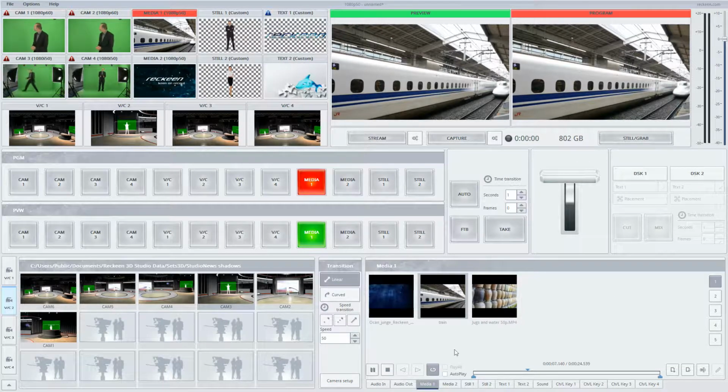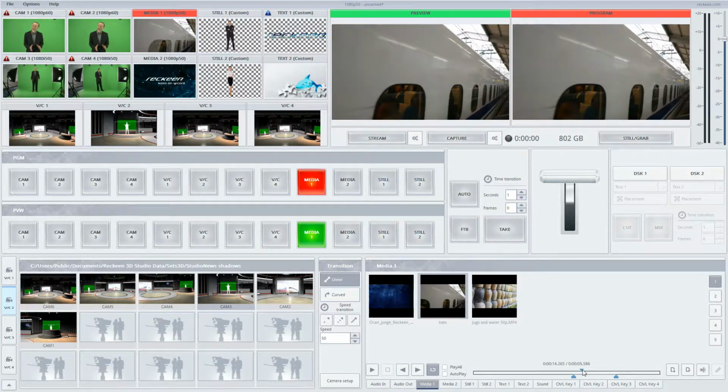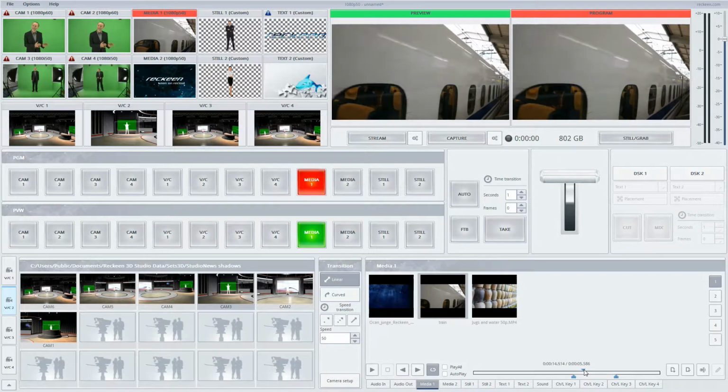Let's grab one of the markers, Mark In. The video stops then. The file's icon in the tray also changes in accordance with Mark In position. The same can be done with Mark Out marker cutting the end of the video. The playback time will only take into account a part of the video between these markers. We can set such markers individually for each file, however, we must first load set file into the input buffer.